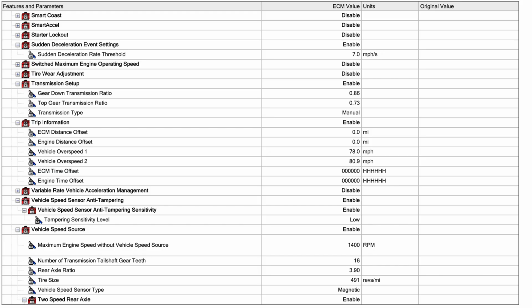You can't add or subtract the descriptions by the toolboxes. So if an engine had a transmission put behind it that actually had an overdrive and not gear down ratios, it would have a different ECM calibration in it that was set up to be matched with that transmission. So you won't see stuff in here that you shouldn't.